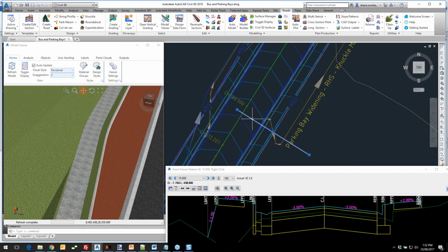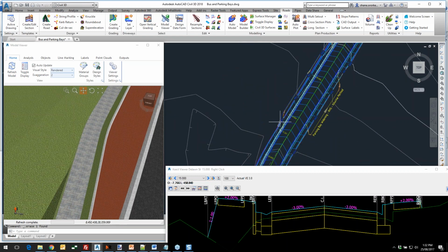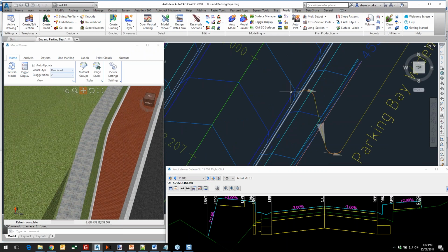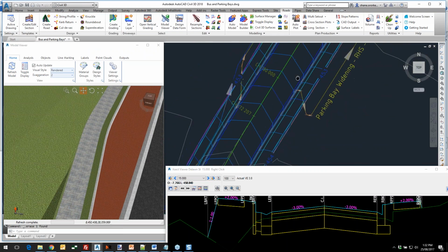You actually need another string. So a knuckle helps you design that other string. We're going to run the knuckle command. Now, I'm committed to us putting a dish in place, really just so you can see how to use a knuckle with a dish. The easiest way to create a knuckle is actually to link the knuckle to the edge of the road and not bother with a dish. All right, that's the simplest way, but we're going to put a dish in.